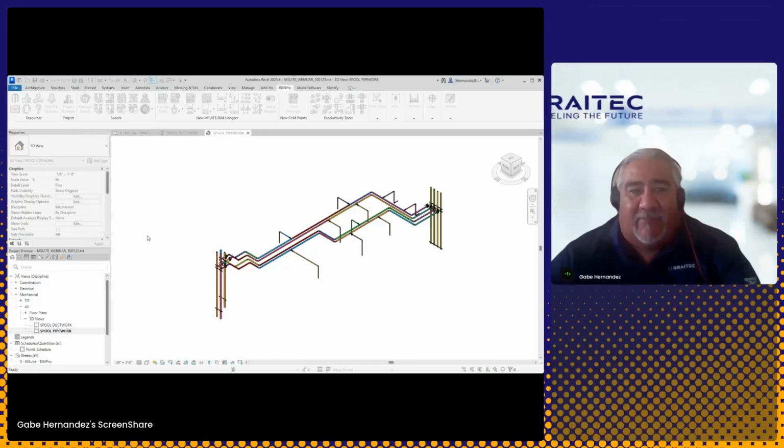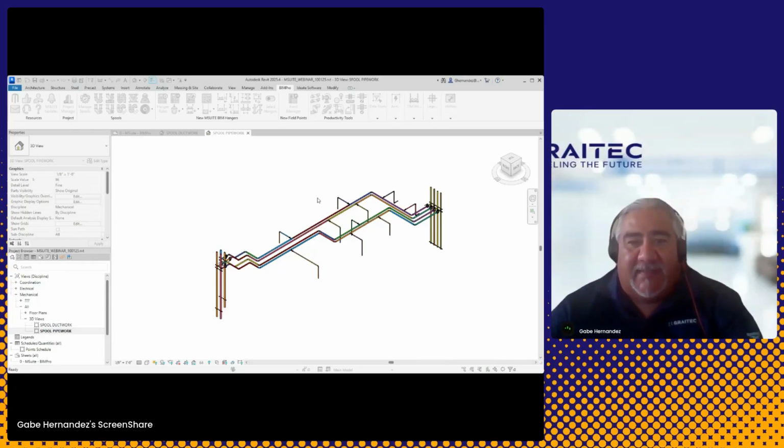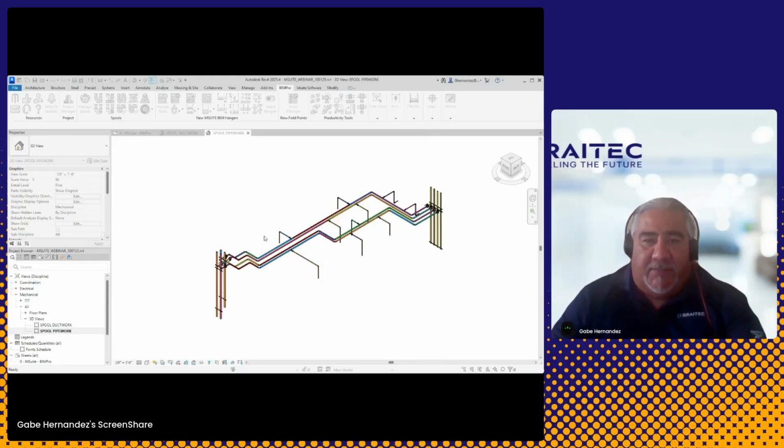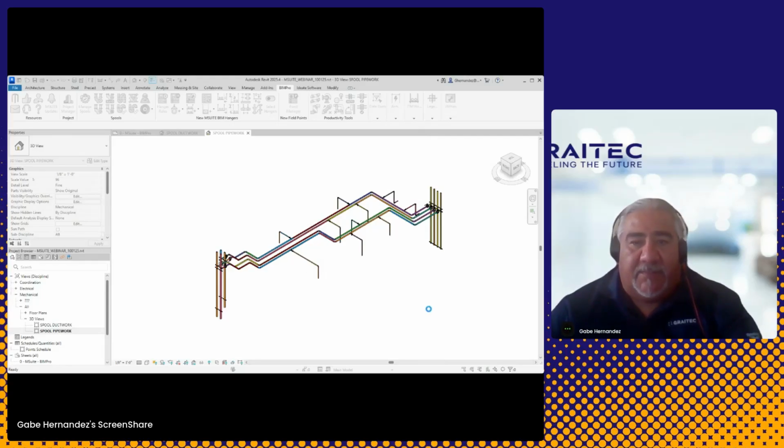All right. So again, once I've generated those 22 spools, they're all my sheets. I can go to each individual sheet to confirm, right? I can then export these sheets out here. I'll do the export and I'll just put this on my desktop for now. I'll create a new folder and I'm just going to call this PDFs. I'll select that folder and I'll export these out to PDF, and you'll see in this directory them start to populate in here.